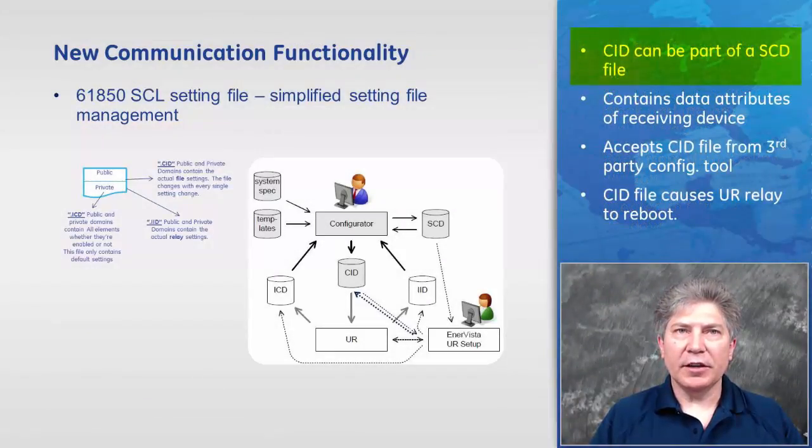The CID, the configured IED description file, describes the required settings of an IED and is intended for transmission of configuration from an IED configurator tool to the IED. The CID file can be part of an SCD file, which we'll talk about next. When importing an SCD file, the EnerVista UR Setup strips out the UR relay portion and creates and sends a CID file to the UR device, when IEC 61850 settings are involved.